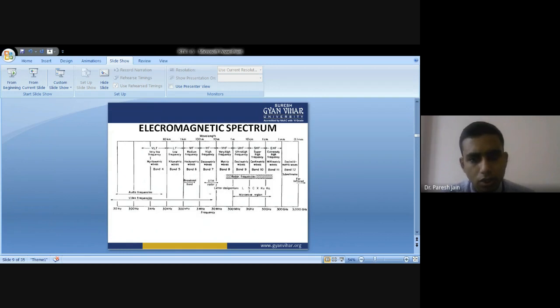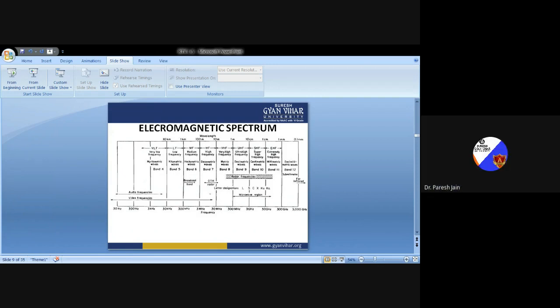Some part of the echo signal is received by the parabolic antenna, the same transmission antenna, and some wave from the aircraft is reflected in another direction, which works as wasted echoes, that is, unwanted echo. We are not able to detect that type of signal. So the wanted echo signal is received by the antenna through the duplexer, the switch that works between transmission and reception on the same antenna. Then the echo signal is further processed in the receiver system.